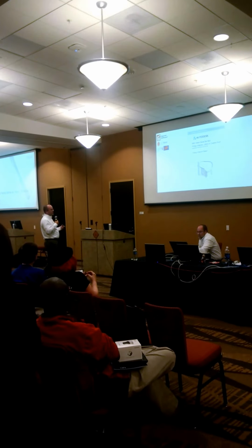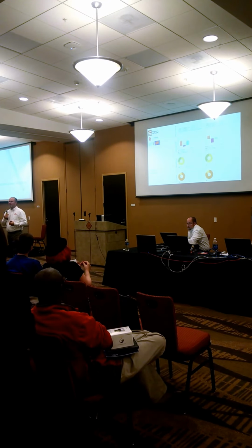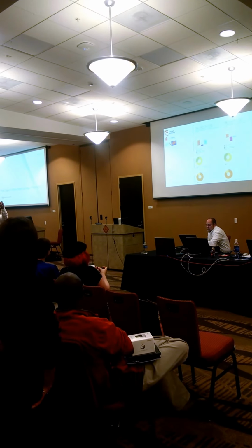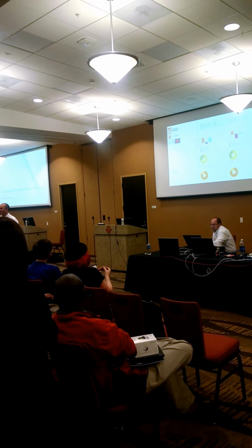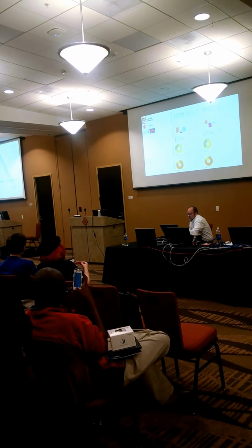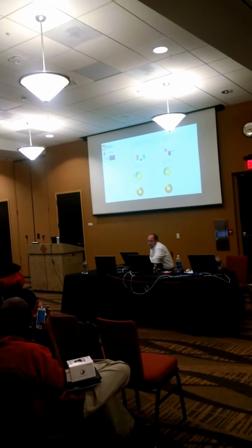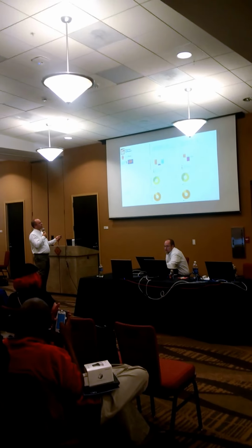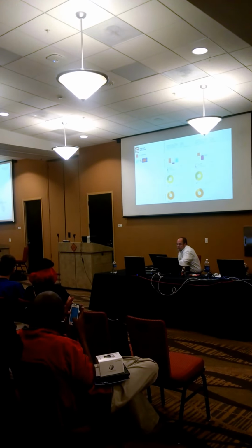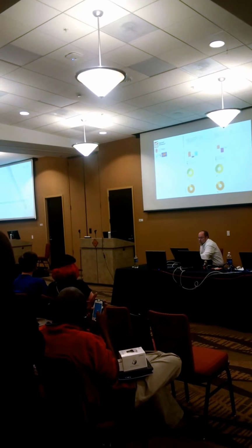And then we took that information out to do an energy analysis, basically. And this is another set of tools that are available not only in the product, but it's actually interconnected to the web or up in the cloud. So we're not doing that processing power on our specific computer. We're taking this, saying, here's my model, again, that wagon wheel, if you will, exporting it out to let it analyze and tell us some different variables about the building, getting into the annual energy use, carbon elements related to that. Just by it being placed correctly on the site, it's actually pulling up some of the GIS data, some of the government data that relates to how much the cost of electricity is in that specific area.